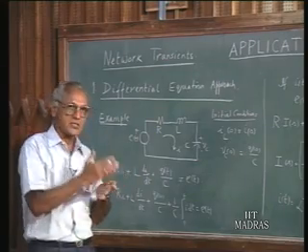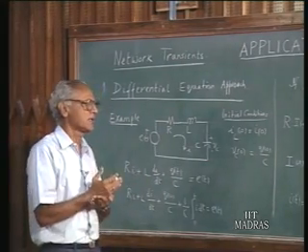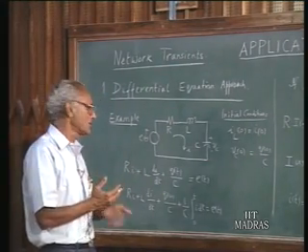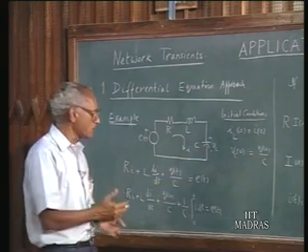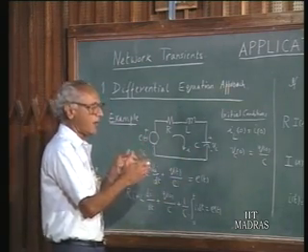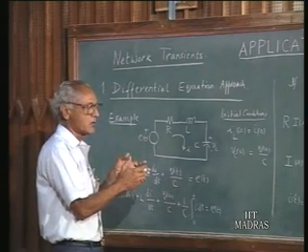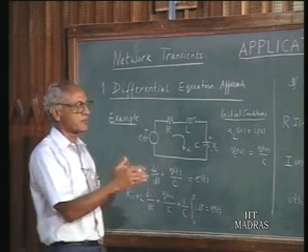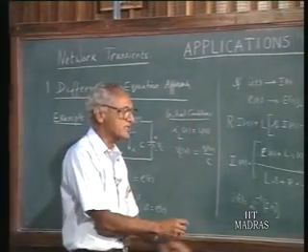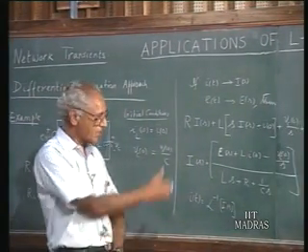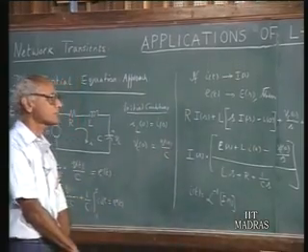But if 0 minus and 0 plus conditions are going to be different, and you want the solution from 0 minus, you can substitute straight away 0 minus conditions. In the classical differential equation, we are perforce required to substitute the conditions as 0 plus. Sometimes if there is a transition from 0 minus to 0 plus, you have to make a separate evaluation of the 0 plus conditions. That is avoided in the Laplace transform technique, as we can see here.